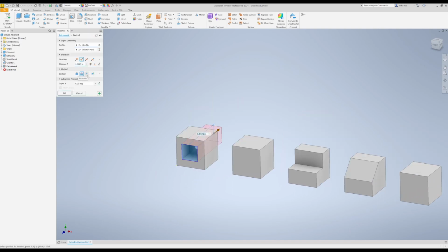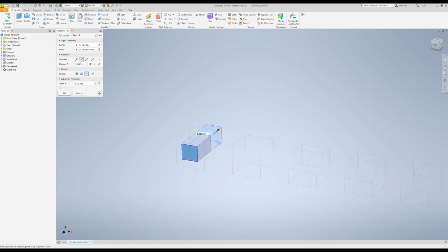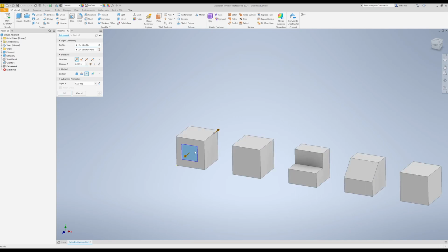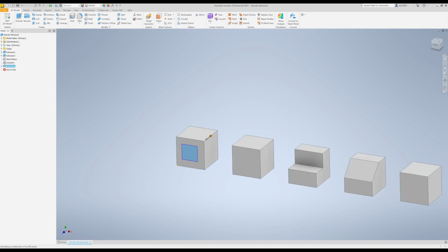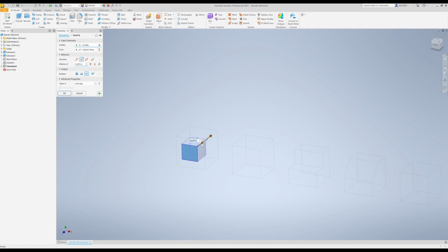Now, we can use the intersect tool. The intersect tool is pretty cool. If you click on that, it will take a previous shape that you've had, like this cube, and wherever you extrude it, it will keep that much of that shape. If I click OK here, it cut out everything except the area that was inside of my 2D shape that I extruded. If we go back into there, if we only used half of it, it would only keep that little part of that shape.